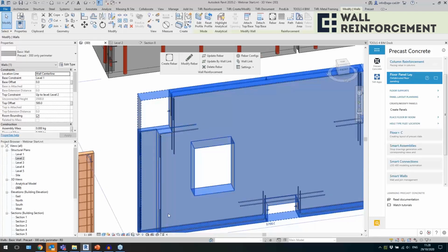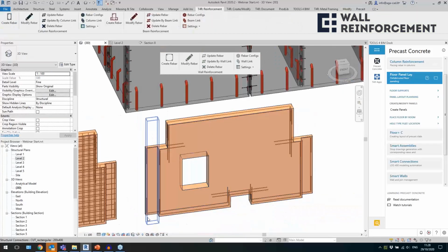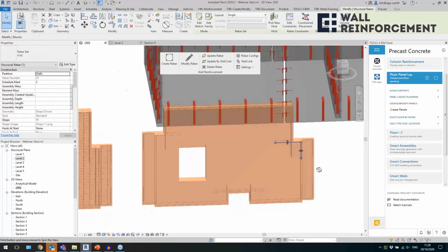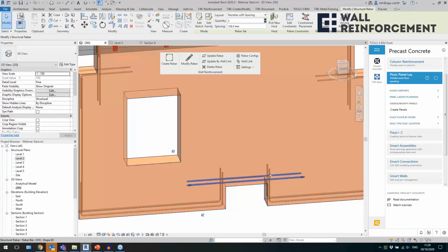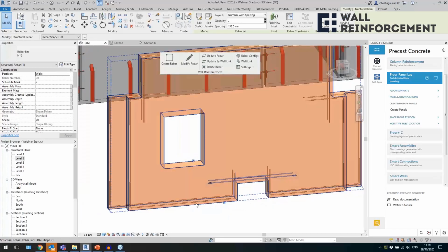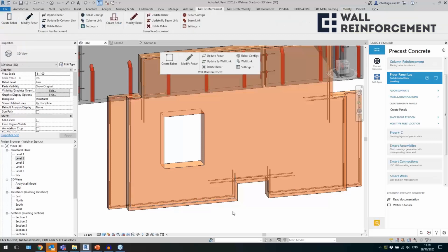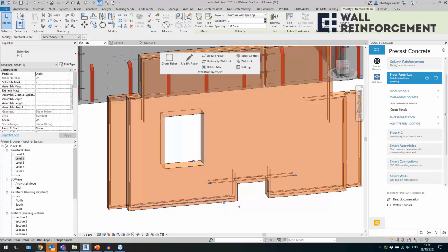That's why it's following, even if I have this kind of cutouts, shape edit of the wall, it still follows and places the rebars. And this searching distance, what I mentioned is that, for example, this one is not placed at the same position. It's searching. It starts searching from 50 millimeters for this kind of horizontal cuts.